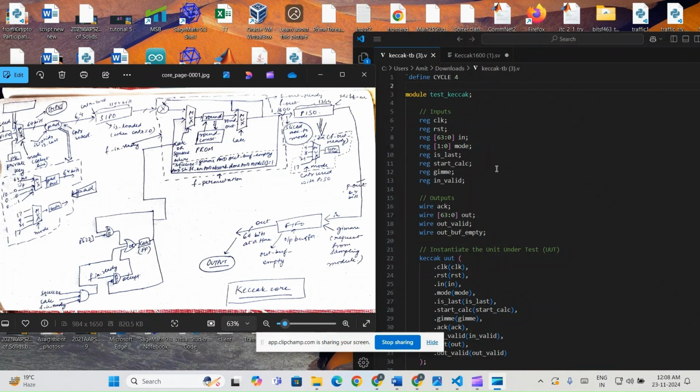Here we can see the block diagram of the overall system also given alongside the provided code of the test bench. The purpose of this test bench is to validate the design of the Keccak core, that is a cryptographic primitive critical to the implementation of secure PQC algorithms. The test bench ensures that each module in the Keccak core functions correctly, including input handling, padding, permutation, and output generation. It systematically verifies correctness by applying a set of stimuli and observing the outputs for the expected behavior.